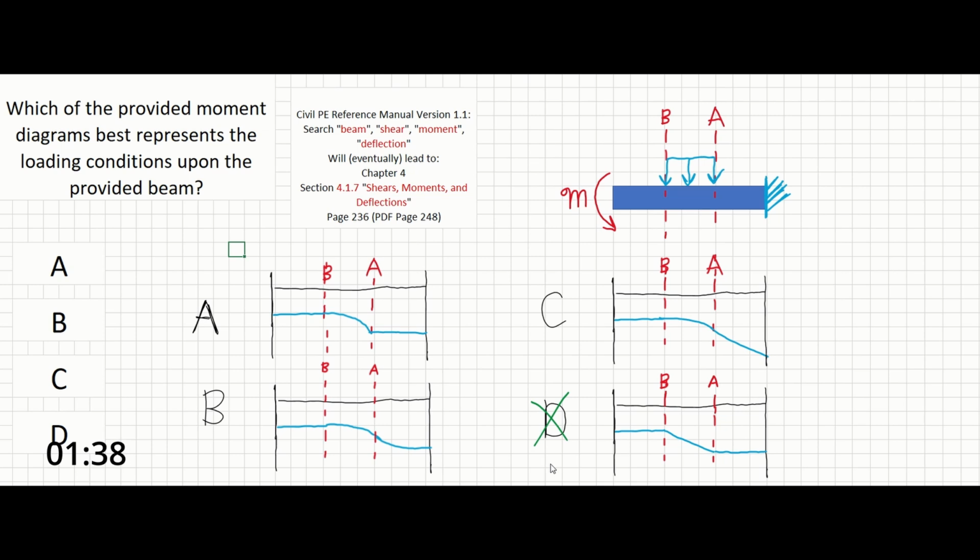Finally, there is a section from A to the point where the beam is connected to the wall. The first section closest to the anchor point looks like examples 21 and 22 in the manual, in the sense that there is no additional force applied to that section, but the moment is still being impacted linearly from the distributed load in the section next to it. This will instantly narrow down our answer to C.